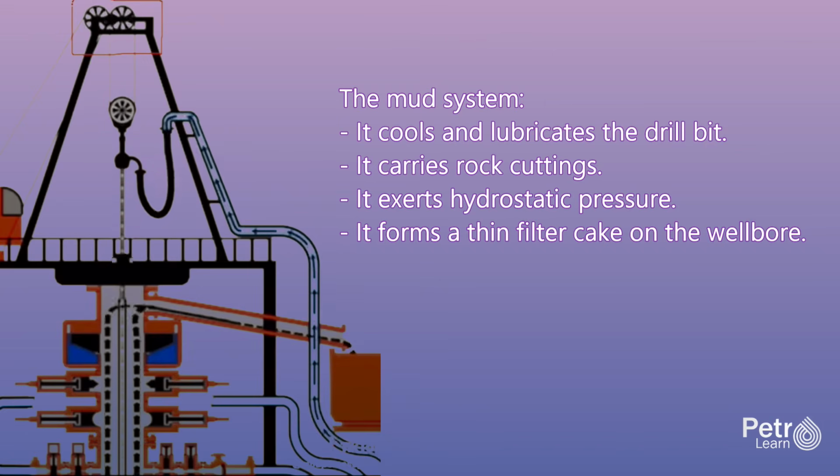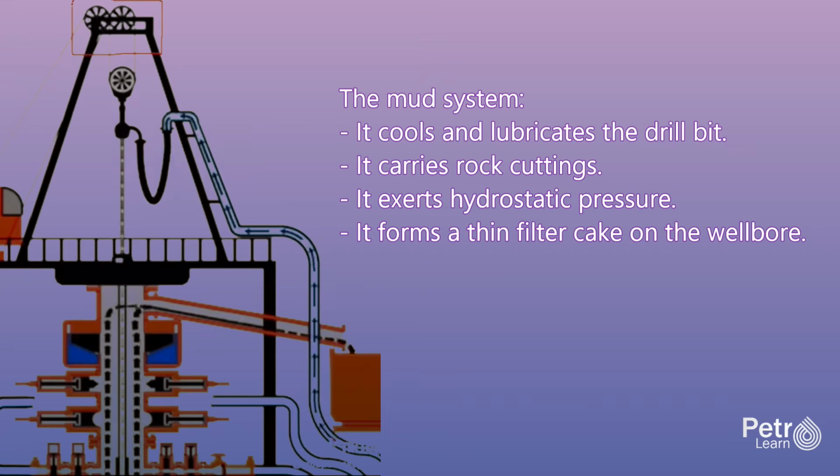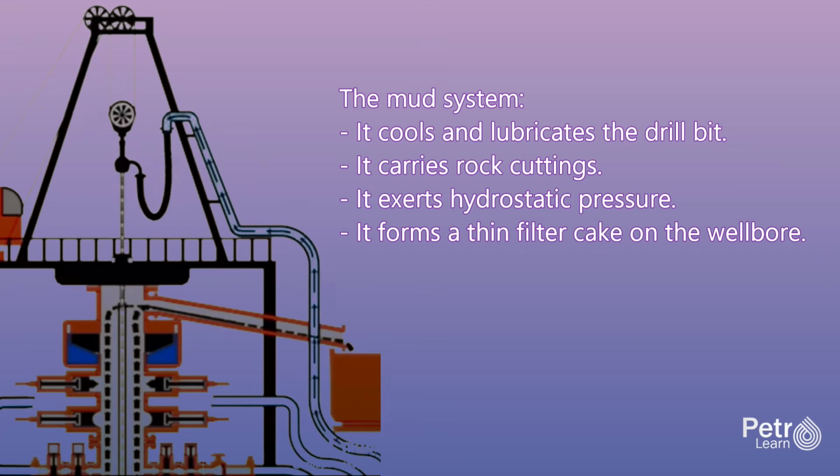The mud can be water-based using fresh water or brine as the base, or oil-based using diesel or mineral oil. Additives control its properties. Barite is added to increase density and hydrostatic pressure. Bentonite clay increases viscosity. Polymers control fluid loss. And various chemicals adjust pH, prevent corrosion, and stabilize shale formations.